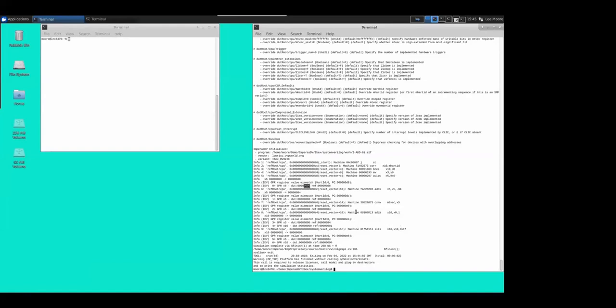And so if we continue executing, remember I said that X10 also has a fault in it, and so here we see an X10 failure because at this point we've done an add immediate targeting X10, and again the RTL is saying that it has the value 0 in X10.